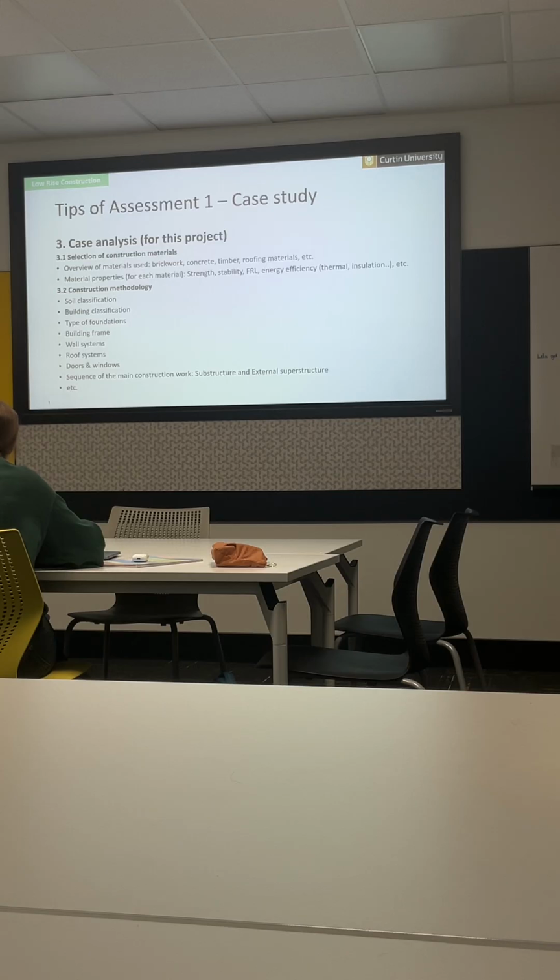Right, that's very good. If you cannot find the soil classification in the documents, as a construction manager, you probably have to hire a professional to conduct an investigation of the soil, right? This is a very important step before you determine the building classification and the specific construction methods. And this is how you write that.